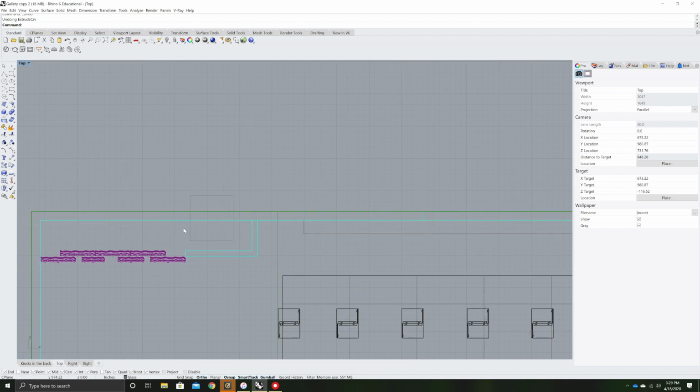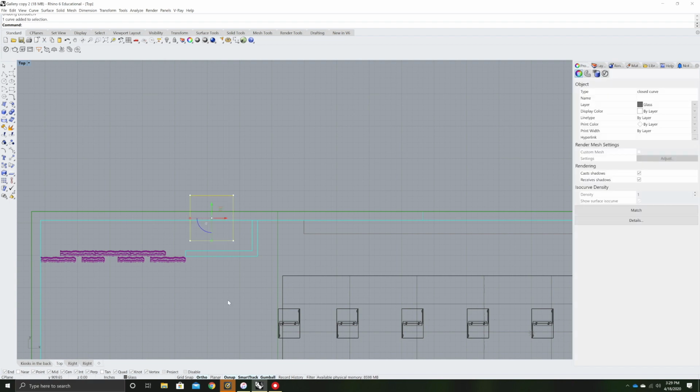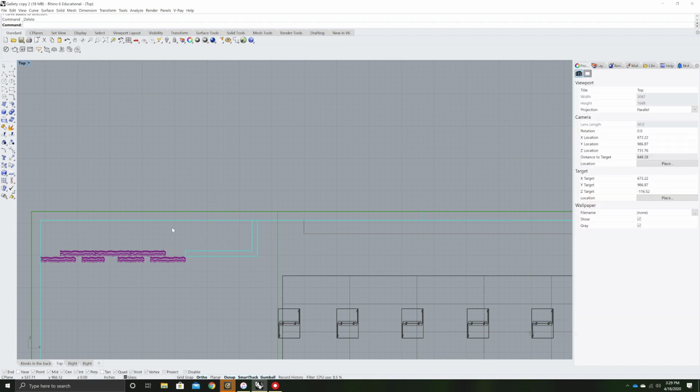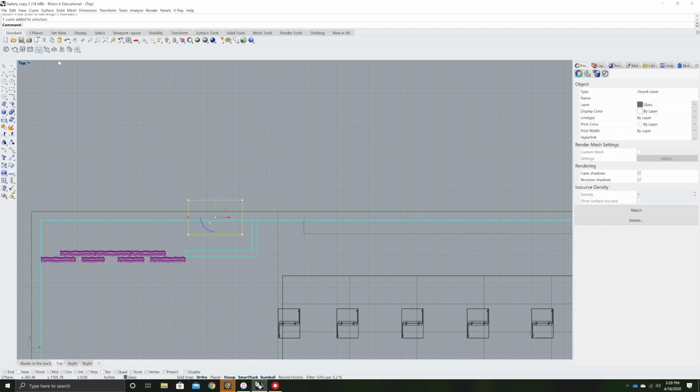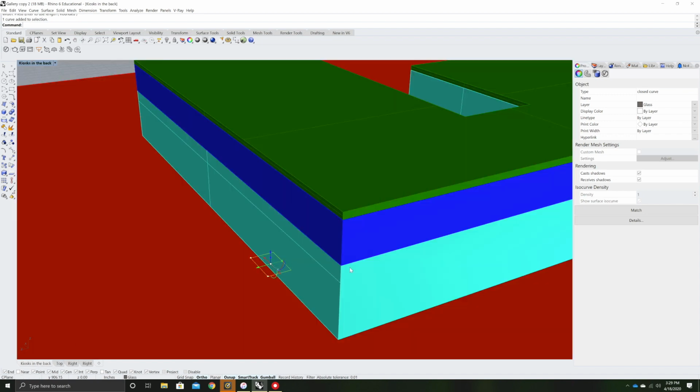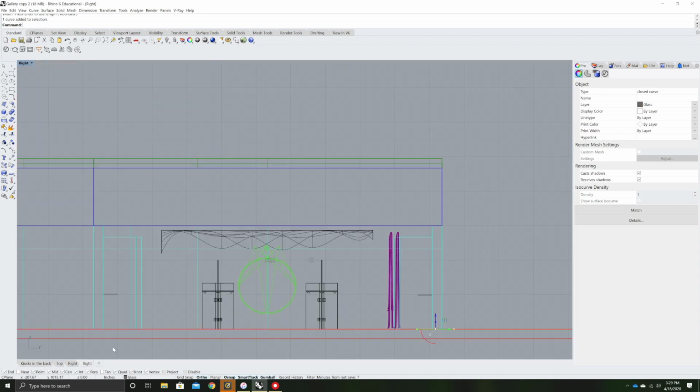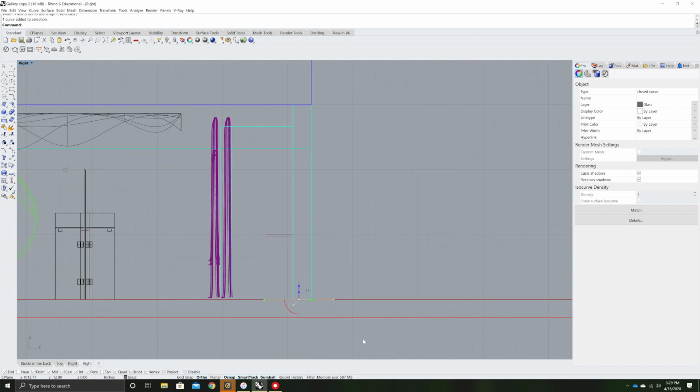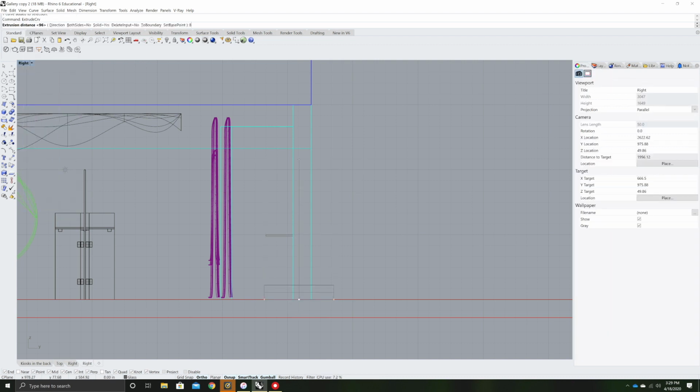So I'm going to start from right here, and I'm going to click on the rectangle tool, or type in rectangle, click, and start to drag out, and then I'm going to do a 60-inch door, enter. That gives me 60 inches locked in from left to right, and then I can just overlap it. Because I created my gallery at the 0 point and then extruded my floor below, I know that this rectangle is right on the floor there. So I can extrude this up, and I'm going to go up 8 feet.